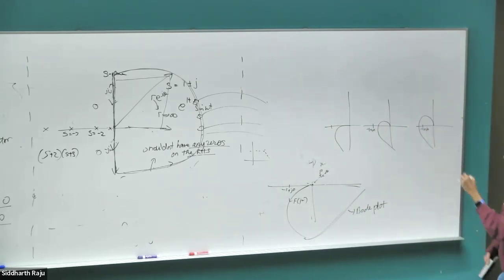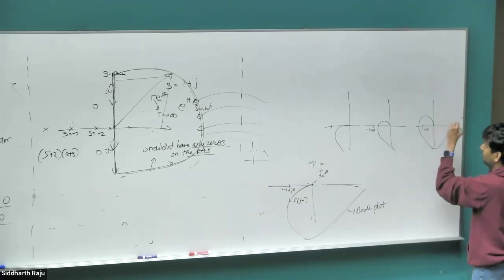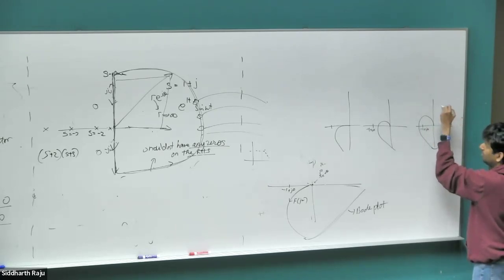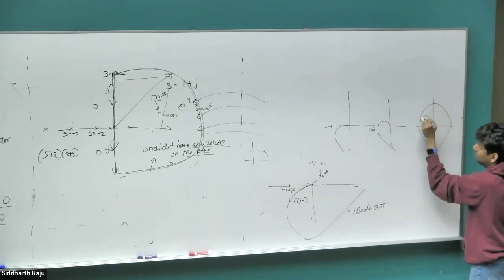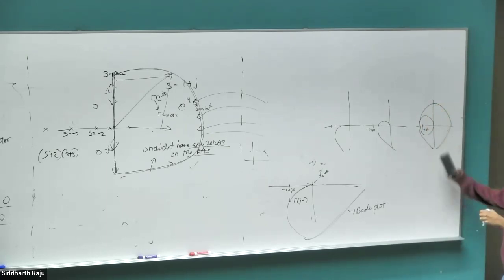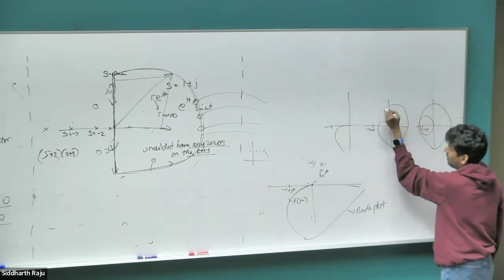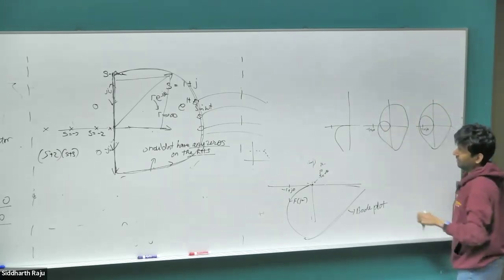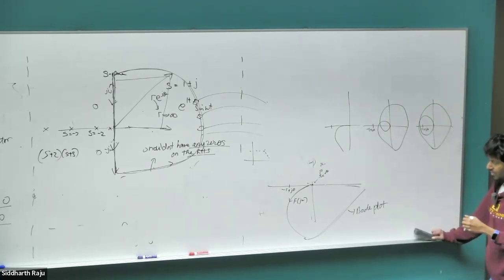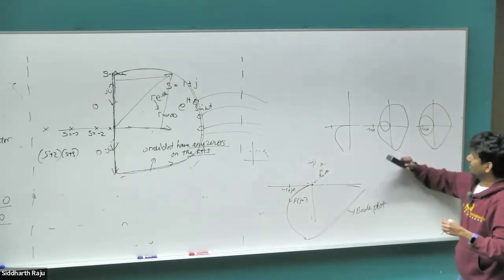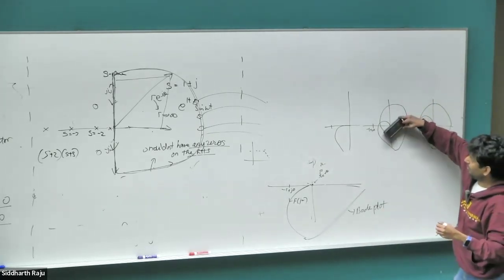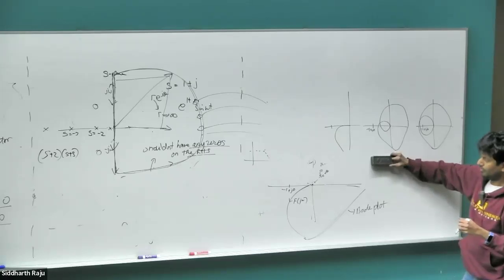Right? Because this is only one half of the plot. So let's say this is the plot you get. The other half is for g of negative j omega, which should come out as the complex conjugate of this. So when you plot the whole plot, you would get a negative 1 plus j0 encirclement. If you had something like this, that wouldn't happen. It will encircle something, but it's not negative 1 plus j0. So the requirement for stability is all I have to do is look at the Bode plot, and my graph at no point should enclose the negative 1 plus j0.